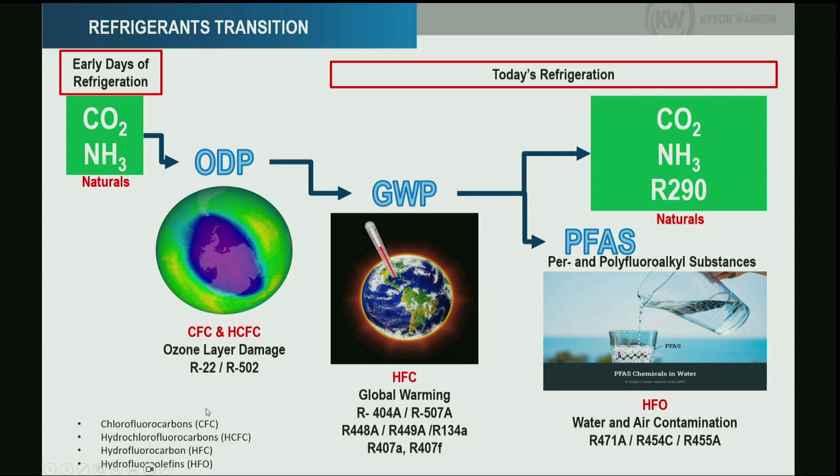So those refrigerants do have a number assigned to them, the GWP number. That number is relative to CO2. Basically, the higher the number, the more effect they have on global warming potential. So CO2 is referred to as GWP of 1. Some of those refrigerants have GWP numbers in the thousands, almost 4,000. That means they cause, let's say, 4,000 times more damage than CO2 when they get released to the atmosphere.